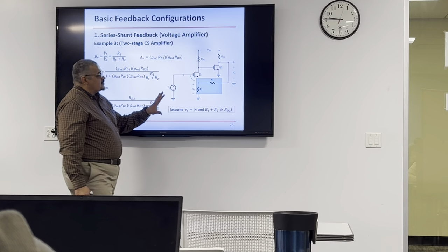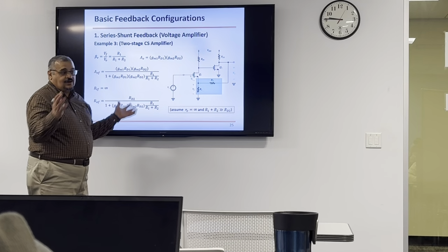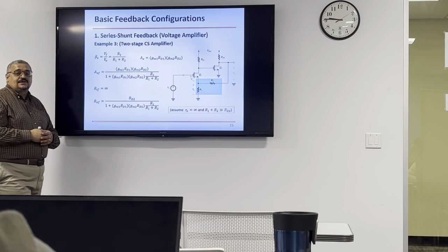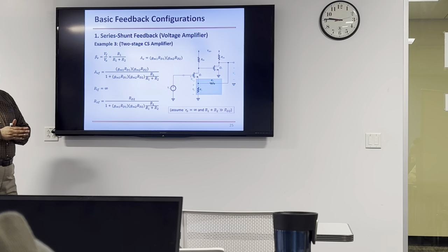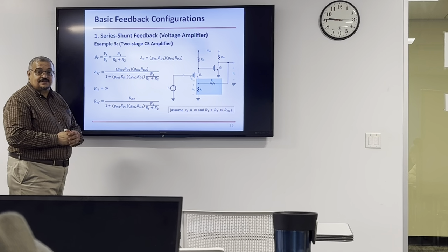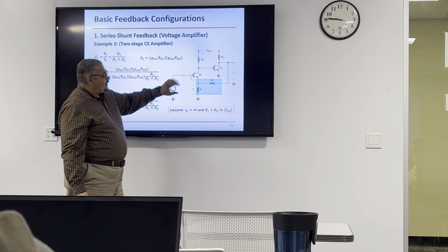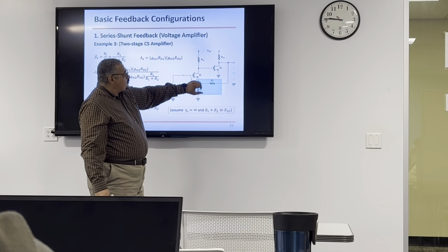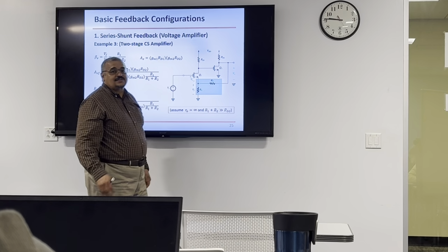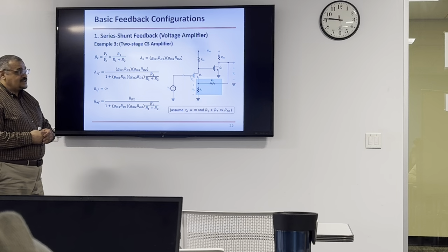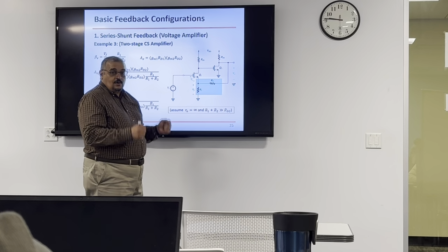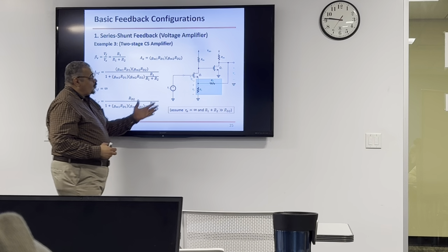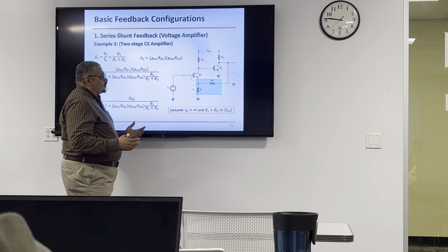So the circuit without feedback has much larger gain, which is good, but it's very sensitive to other variations and affected by other things. And the bandwidth is not large. It has many disadvantages. So instead of getting one large gain from one stage, I can solve this by cascading several stages and getting the larger gain from these stages. But each stage has to have feedback to be more robust and stable, with higher bandwidth, improved input and output impedance, lower noise effect, and so on.